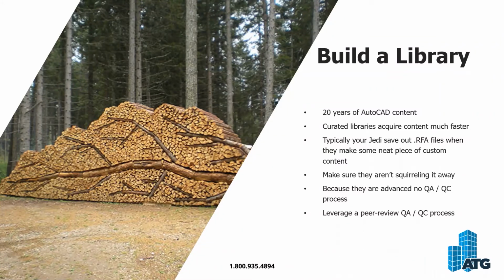You guys probably have, if you're like most firms, about 20 years worth of AutoCAD content. I have seen firms have a pretty successful schedule of transitioning old DWG drafting details into drafting views in Revit, and then converting that line work over to be detail components so that you get the added strength. I don't need to talk you into it, but you need to have a phased approach of bringing your CAD content forward as Revit assets and build that into your library.